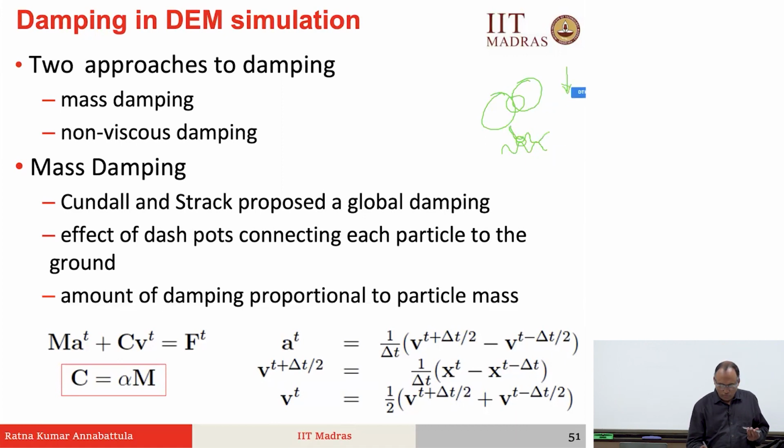Although your force is the same, force by area will be very high because the area is small, and as a result the local stress may reach the yield strength of the material, and hence there will always be some local plastic deformation. That is something we are not accounting for when you are doing pure elastic contact constitutive law. So what is the way out?